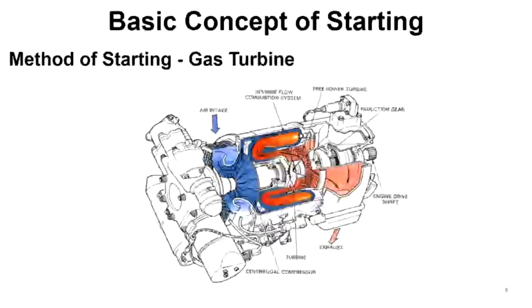The starter consists of a small, compact gas turbine engine, usually featuring a turbine-driven centrifugal compressor, a reverse flow combustion system, and a mechanically independent free power turbine. The free power turbine is connected to the main engine via a two-stage epicyclic reduction gear, automatic clutch, and output shaft.